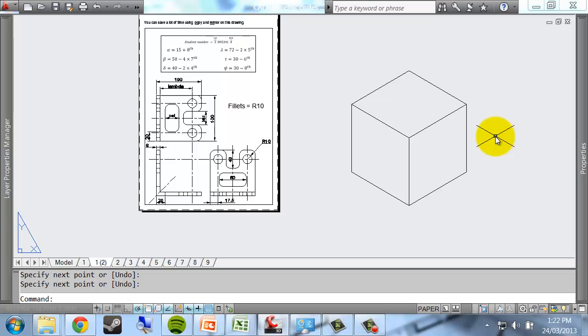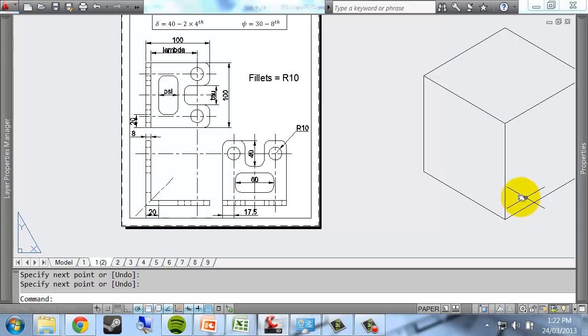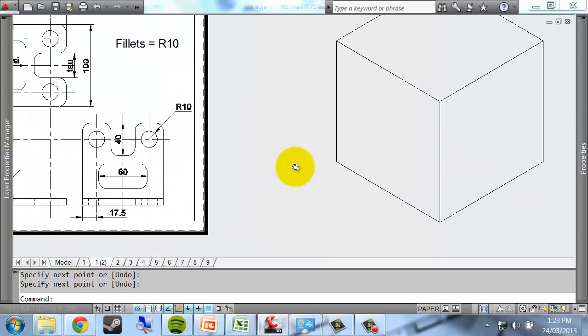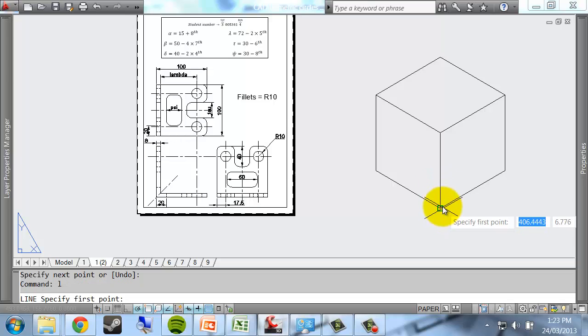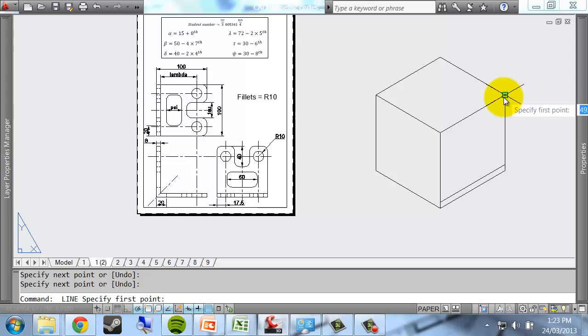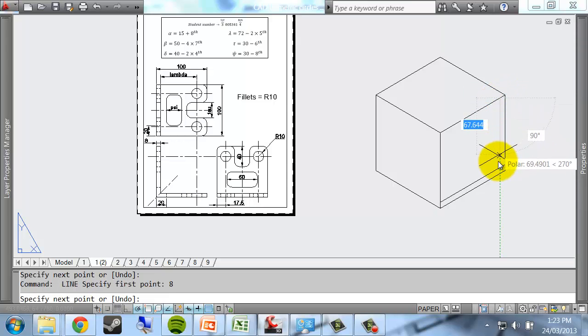Now it's actually a pretty thin shape, so it's got this L bracket looking thing in here. From the side on, we'd only see I suppose an edge which is how many units? 8 units thick. So I'm going to draw a line along here which is 8 up, goes all the way to the end, another one here which is 8, comes down there.